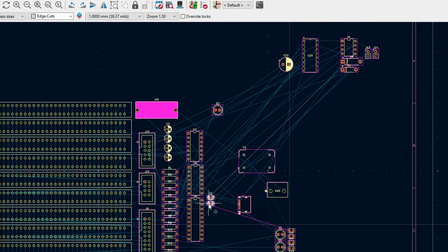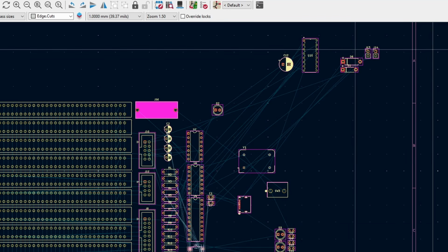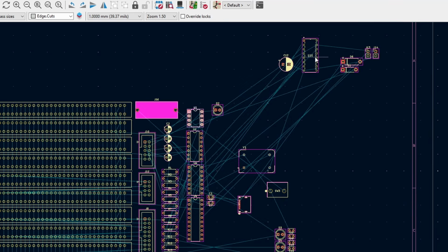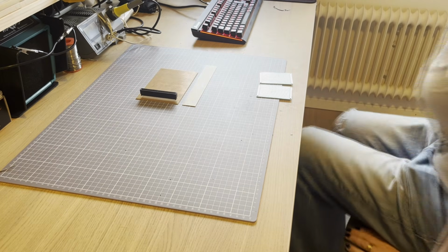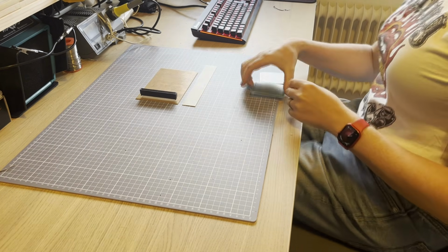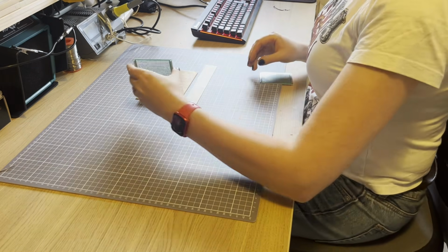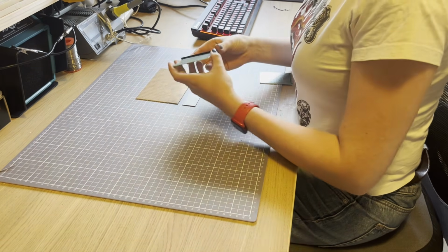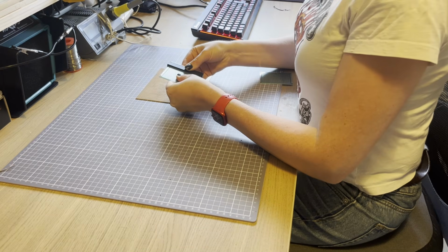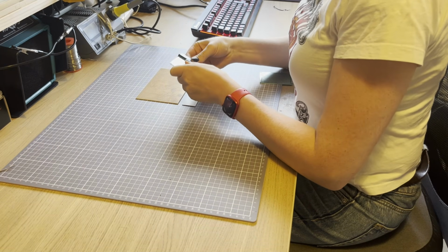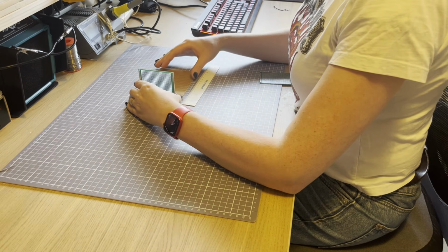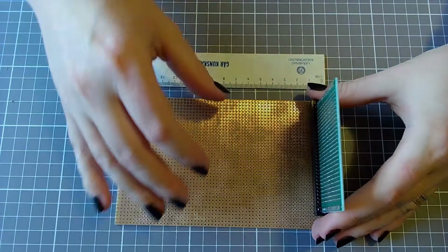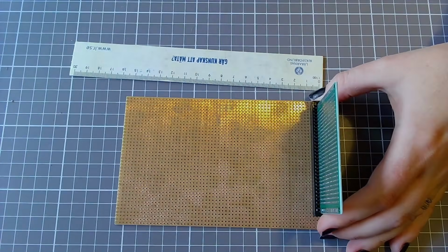Eventually I realized that I needed to stop searching for the perfect layout, and instead I needed to make myself some constraints. Ironically, adding constraints actually makes a lot of problems much easier to tackle. I figured that once I knew roughly how large the board should be, I could create a boundary that I could place the components inside. And that would dramatically decrease the amount of possible layouts.